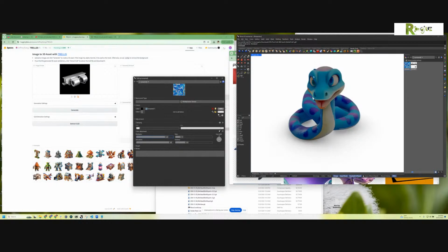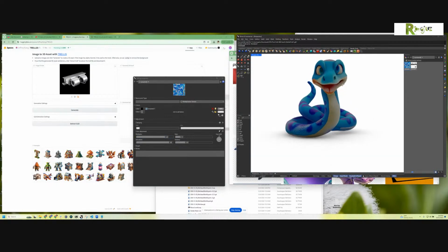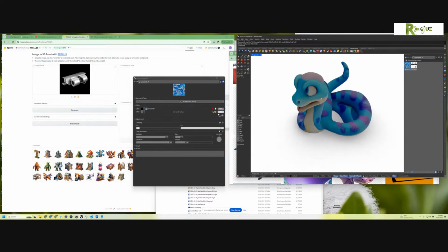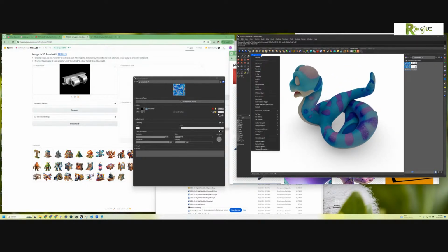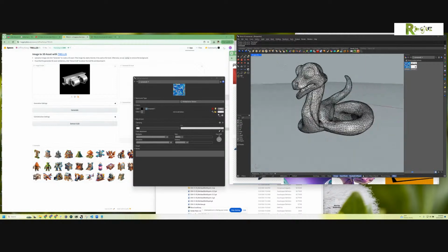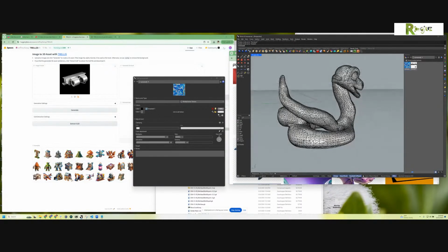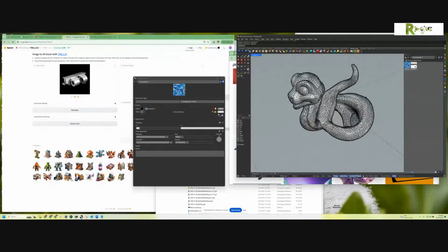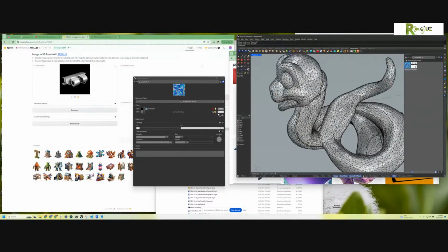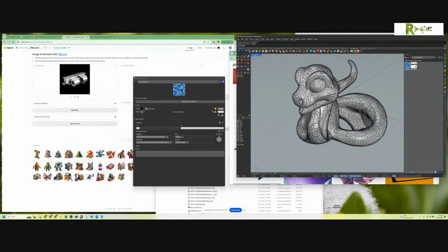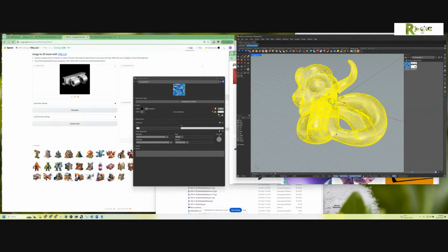If you tried to model that in Revit, you'd be dead. But the more important thing is a lot like our roof that we were talking about. We don't try to draw all those standing seams. He's getting scales with a bump map. That's generally how we try to get that texture on there. The snake looks smooth, but when he goes back to the shaded view, you'll see it has scales. It has bumps on it.